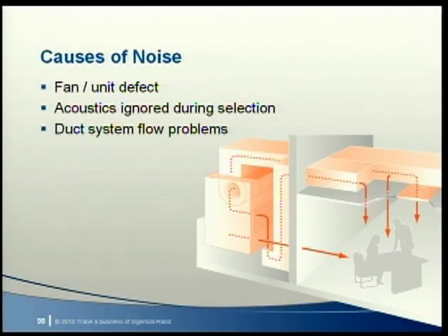Dave? The most common complaint I hear about is fan noise. All types of air-moving equipment have the potential to be noisy. Fans generate sound, and if that isn't taken into consideration, the result can be noise. I think most noisy fan complaints can be divided into 3 categories. I'll call them unit defects, selection misses, and duct flow problems.